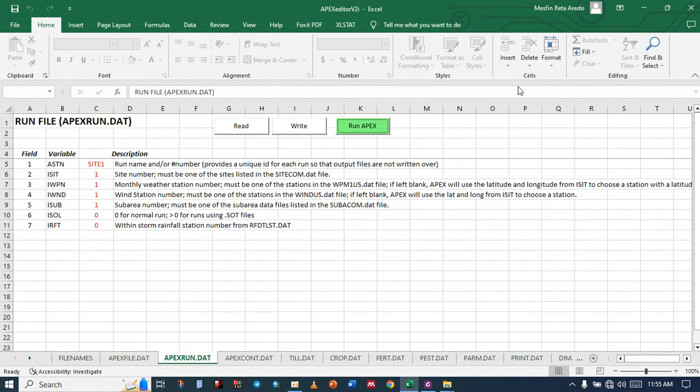But please be careful that you do not use write before reading what is in the folder. Okay, do not use write before reading what is in the folder. If you hit write, it's going to replace the value which you see here in the Excel template, which is the default value, with your actual model. So do not do that. If you do that, you will be stuck.